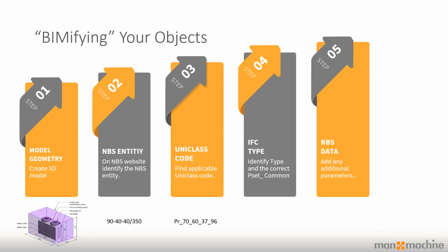The next step is to give it a Uniclass code, a classification code. We commonly classify things on BIM objects to make sure that no matter what it looks like, we know exactly what it is. We should be able to have a load of models that are just made up of very simple representative components, but with a very detailed hierarchical classification code, we can tell whether it's a standard opening, we can tell if it's a wooden door set, a composite door set, a revolving door, or whatever it might be. We have a common classification system that is hierarchical to control that amount of data.